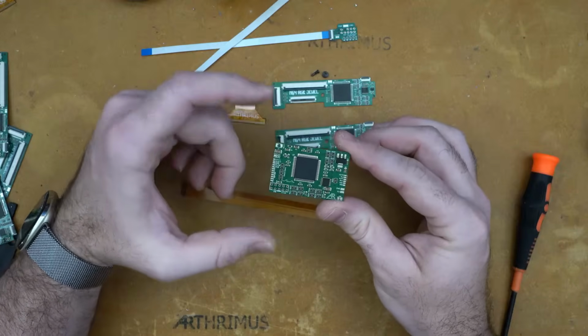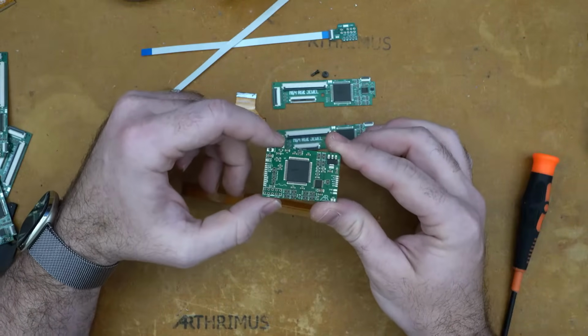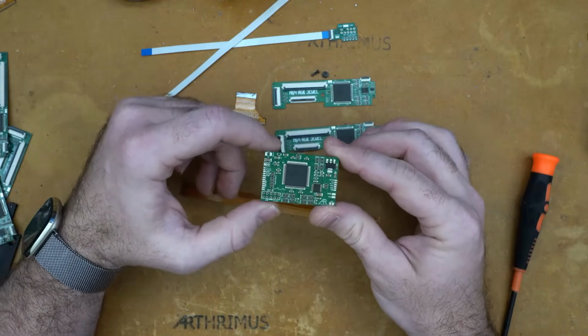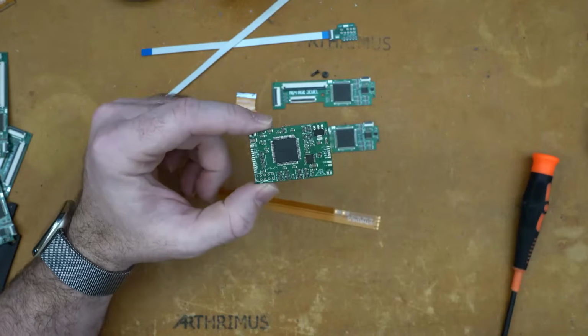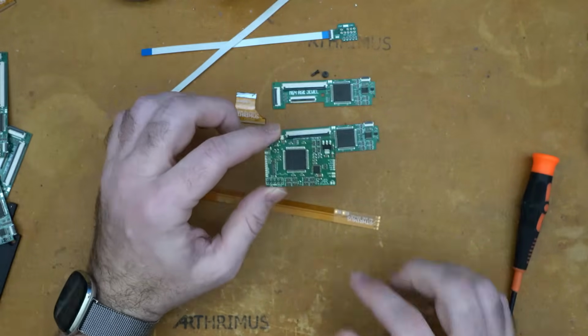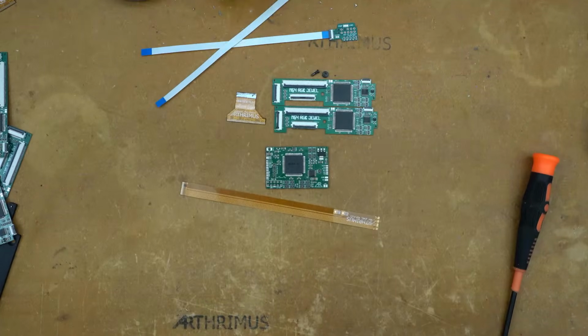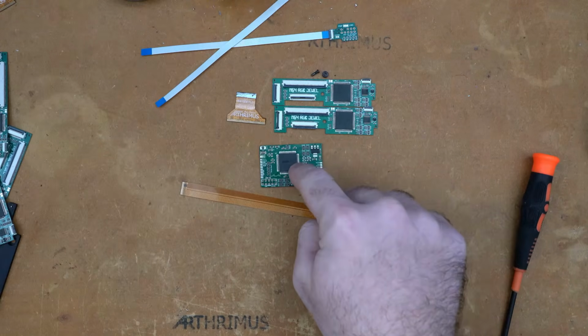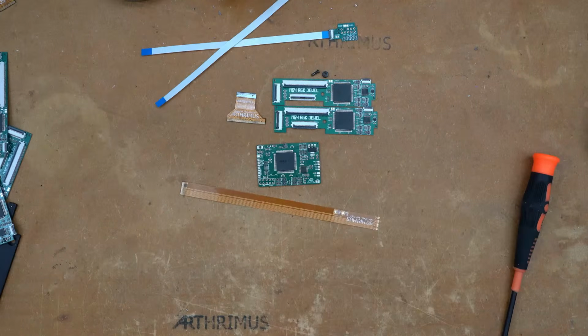I started making these, I don't know, like 2016 or something. And one of the problems with these boards, Tim's early boards as well as Bordy's early boards, was that the N64 has a really noisy 3.3 volt power rail, and noise from the audio amplifier circuit would actually end up in the video signal for these early RGB mods, and it would cause the video brightness to flicker as sound was happening.